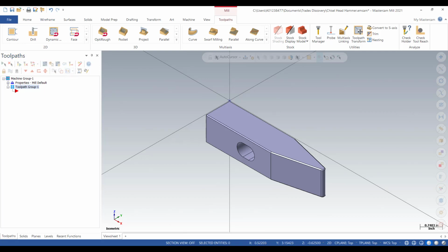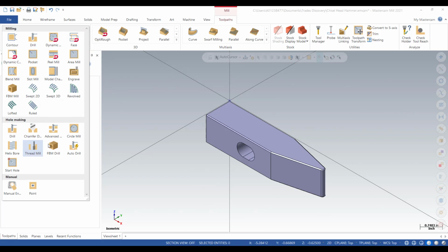Now we're going to go into the toolpath creation. So the first toolpath we're going to try is facing. Basically, we wanted to clean the top face. So all our toolpaths are here, all our two-dimensional toolpaths or 2D paths. If we explore this here, you can see all the paths here. So right now we're going to just try that facing path.